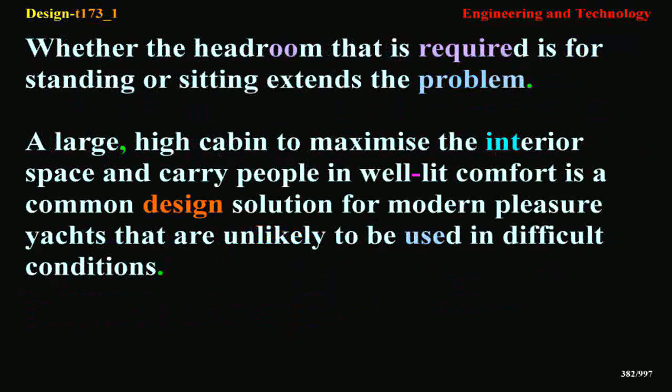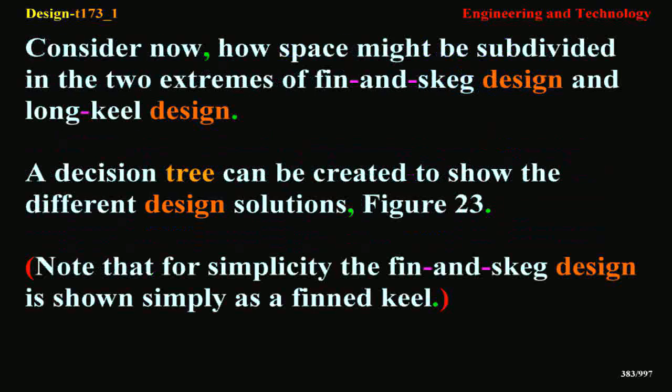Whether the headroom that is required is for standing or sitting extends the problem. A large, high cabin to maximize the interior space and carry people in well-lit comfort is a common design solution for modern pleasure yachts that are unlikely to be used in difficult conditions. Consider now how space might be subdivided in the two extremes of fin and skeg design and long keel design.